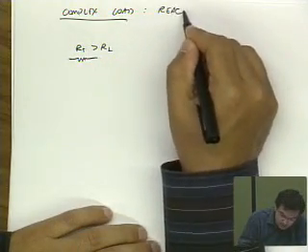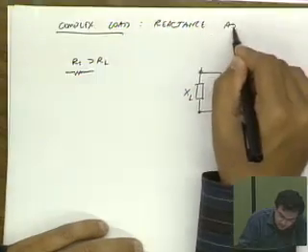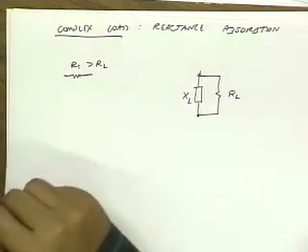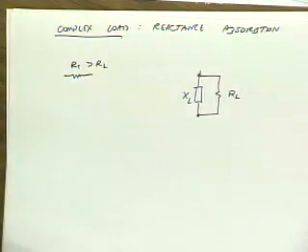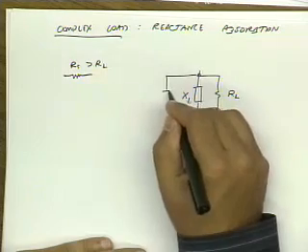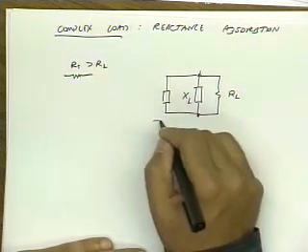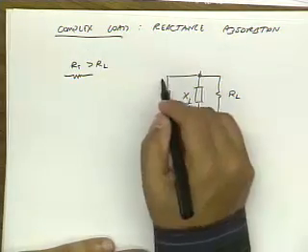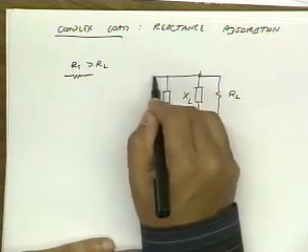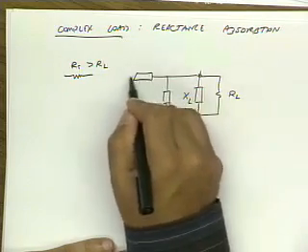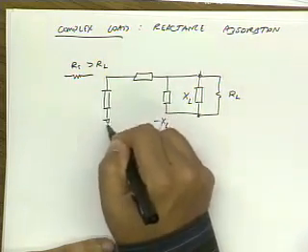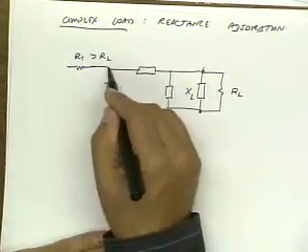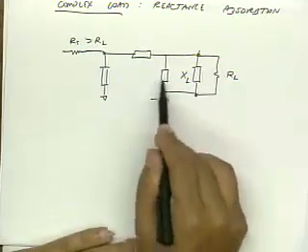Give you guys a hint. It's reactance absorption. The idea is very simple. I can just connect minus XL across here. Now I just have RL, and then I just use my regular network. Right? In many cases, I can actually just absorb this into the matching network.